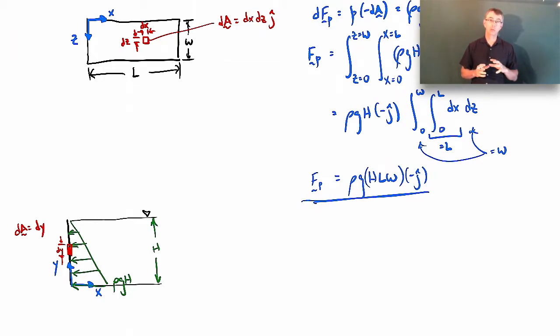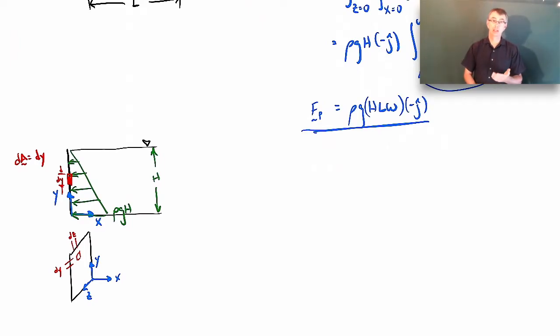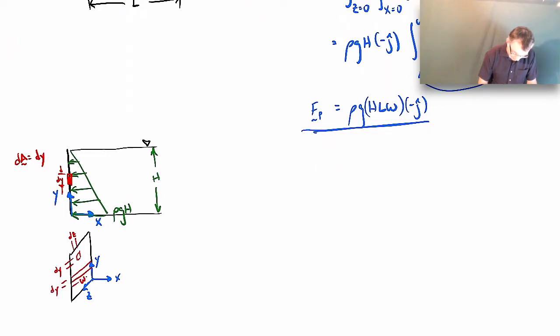Remember, what we want to do is choose an area over which the orientation and pressure are well defined. Another area we could choose would be a strip of area. Let me show that in a picture here. Let me draw the sidewall in more of a perspective drawing, and put in, again, the coordinate system. Here's y, here's x, here's z. One area we could choose might be a little area like this, where this is dy and this distance would be dz. We could do that because the orientation and pressure are well defined over that. Or another area, and the one that I'll use, will be a strip that looks like this, where this is dy and this distance is now w. We could use that area or the little one, either one, because the orientation and pressure are well defined on those areas.